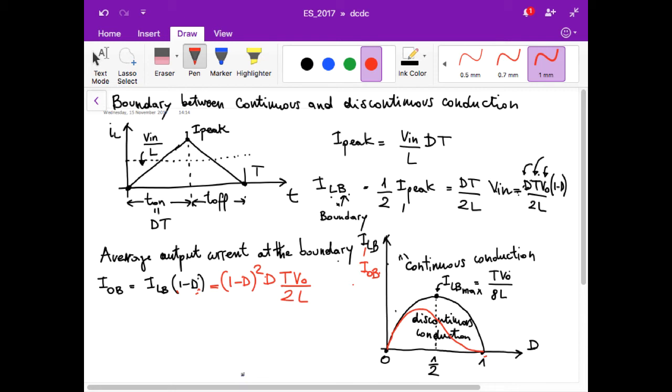Okay. Again, as I mentioned already in the case of the buck converter, we always have this situation in which the DC-DC converter passes from continuous to discontinuous conduction, because as soon as the load requires less current, because it goes in a standby mode, for example, the current drops rapidly, and then the converter has to pass in a completely different mode of operation. Okay.